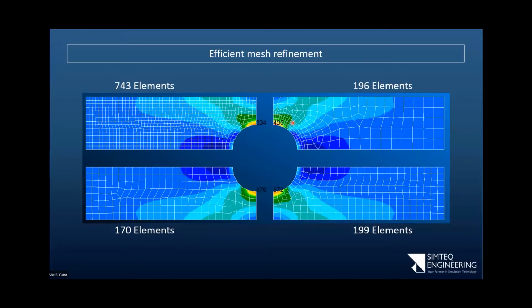On the right-hand side, I split out a small section so that I can get really good quality elements there. And you'll notice that there is a bit of aspect ratio distortion, but no others. In this case, that size is 1 millimeter, similar to this, but it went down to 0.4 millimeters on this edge. And then radially also, I expanded the element size from small to large. So we've got a smaller element in that region. And then the rest I mesh with 3 millimeter elements. So it's significantly larger even over there than it is in this model.